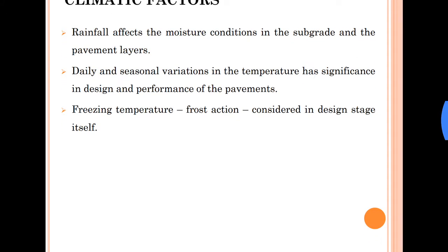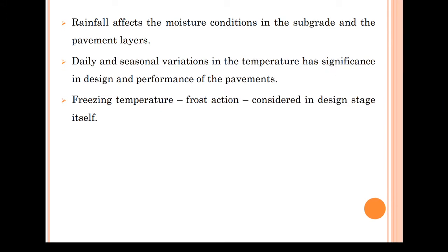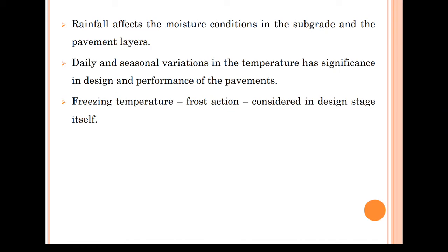These majorly affect the design of rigid pavements, because the concrete slabs tend to deflect when there is a temperature change. And then freezing temperatures. At freezing temperatures, if there is presence of water in the subgrade or the subbase, then that water tends to freeze, and after freezing the volume of water increases.